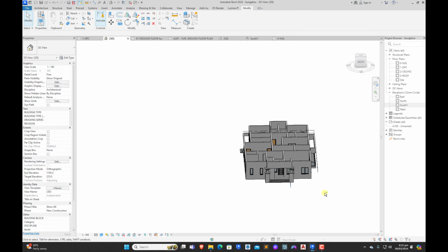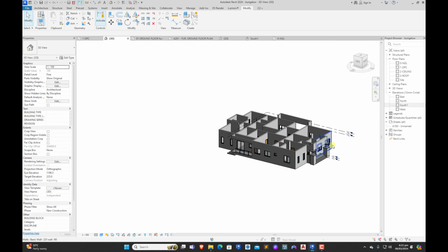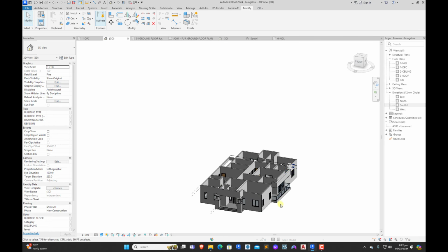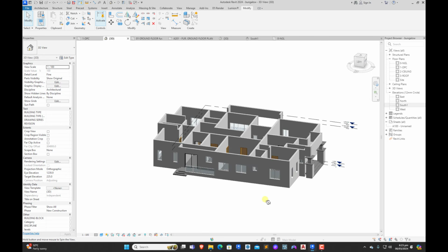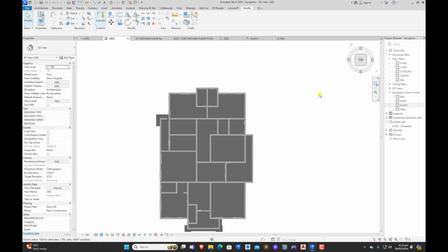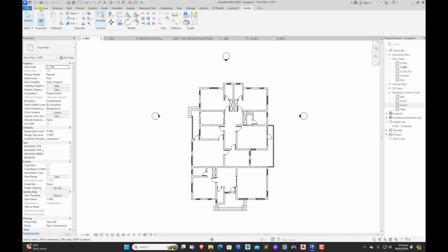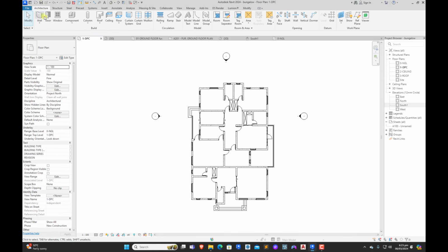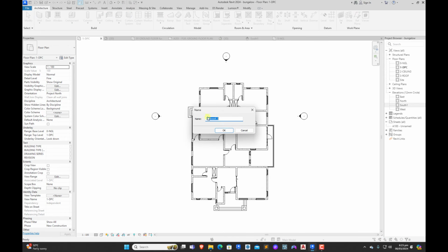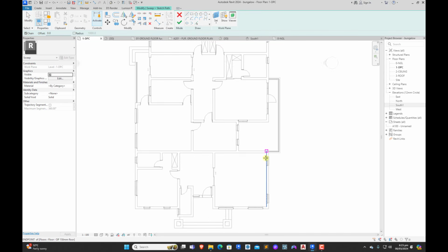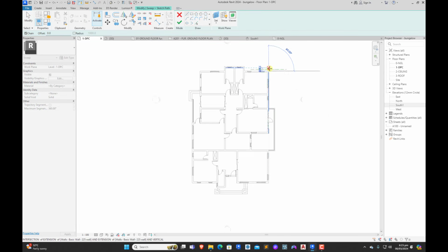So this is nice. Then the next thing we're going to be doing now is to create our concrete fascia. For us to create our concrete fascia, all we need to do is to come under this level, click Architecture, Components, Model in Place, Casework, okay. Then we click on Sweep with sketch path. We're going to be using sketch path, so we click on this.